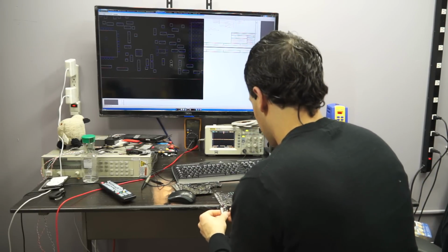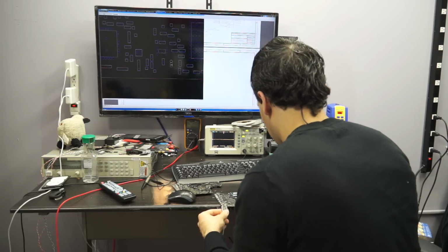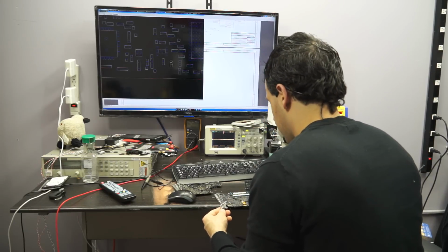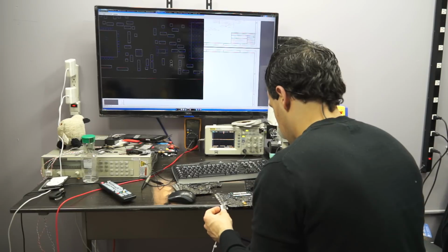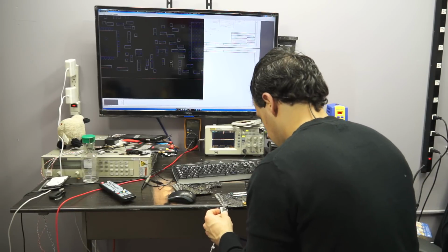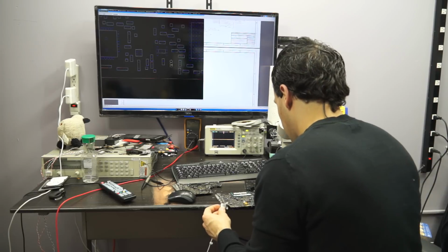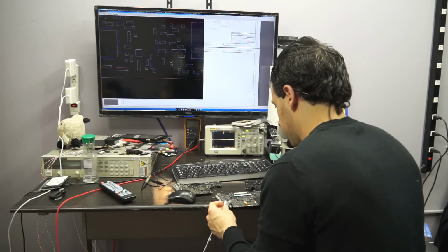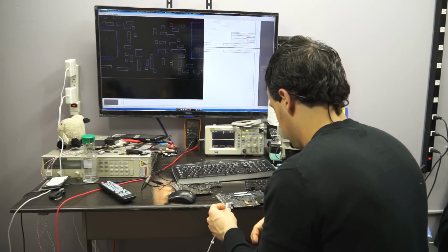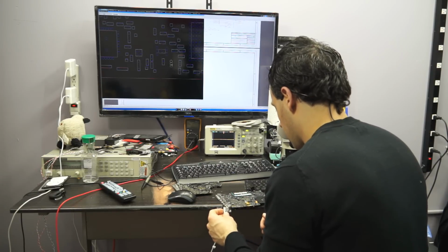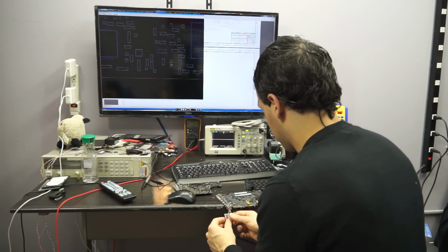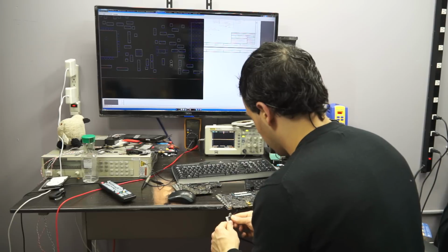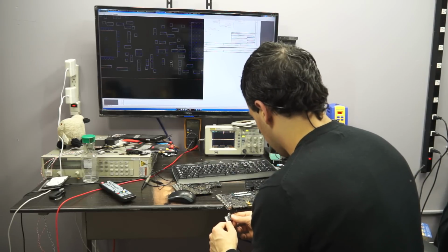So turning this on in SMC Bypass Mode means I'm going to hold down the power button on the keyboard for a few seconds, and then I'm going to plug the charger in. Unfortunately, when I do that, it still doesn't turn on. Except for now, when it actually did just turn on. Now that it's on in SMC Bypass Mode, the whole idea is it's ignoring everything that the SMC is saying to turn on.